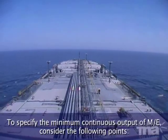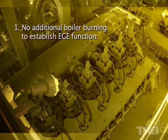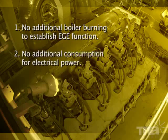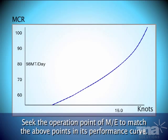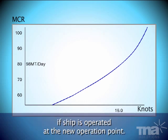To specify the minimum continuous output of main engine, consider the following points. One, no additional boiler burning to establish EGE function. Two, no additional consumption for electrical power. Three, condition of combustion chamber and maker's instructions. Seek the operation point of main engine to match the above points in its performance curve. Calculate how much fuel consumption will be reduced, as explained below, if ship is operated at the new operation point.